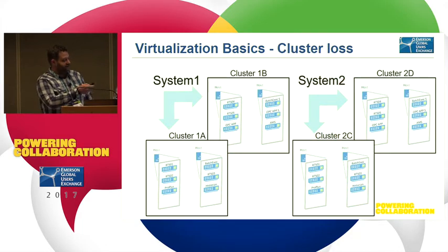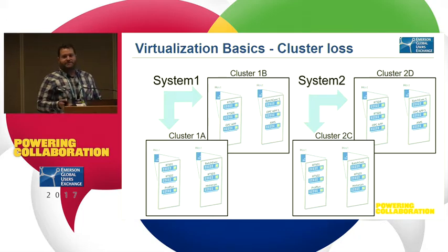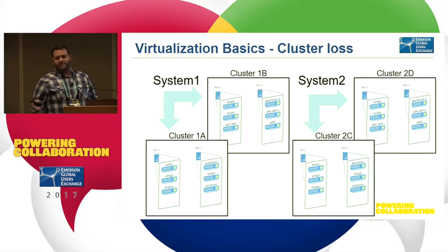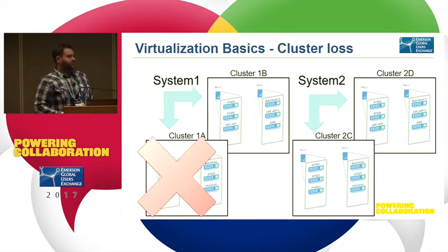So the idea of the cluster is you take these groups of hosts and you distribute the various virtual machines between them so that you have a minimum operating capacity that satisfies your process. So you'd always have a batch executive, you'd always have a Pro Plus, you'd always have at least a certain number of operator stations, even if you lose a whole cluster. You'd have enough capacity between the two to spread it out. It might be spread thin, but typically the idea is that you would be able to retain full functionality.